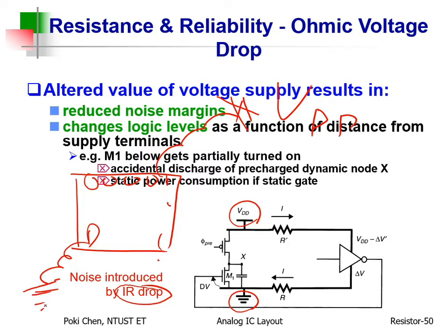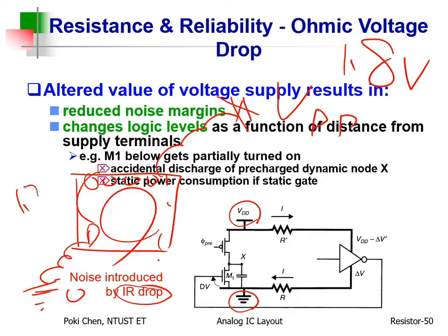Okay? New engineers always think, oh, if I provide 1.8 volts here, 0 there, then my chip will be powered totally by 1.8 volts to the circuit. Is it possible? No. Totally impossible. Why? Because the bonding wires here and there have some kind of resistivity.